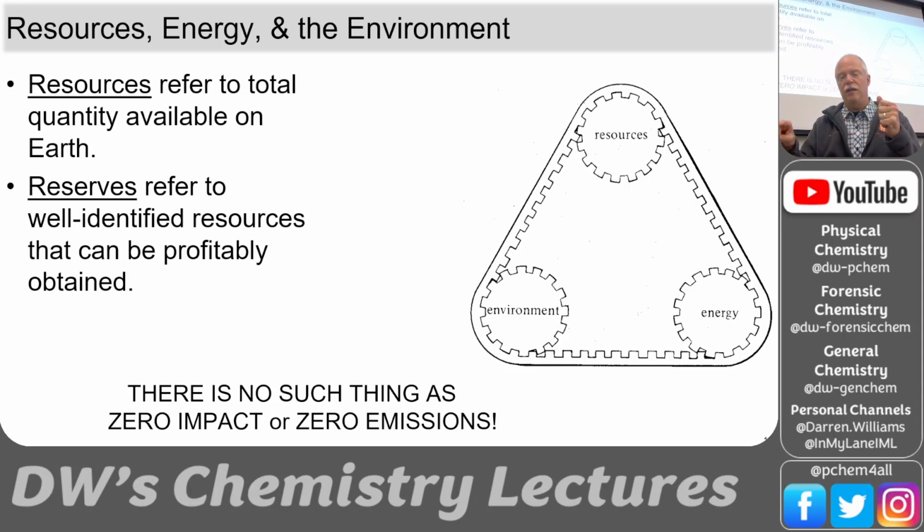So what they do is they get into that rock formation, then they plug the pipe on the top end. It's a horizontal well, but they plug the exit, and then they pump fluid in there at extremely high pressures, and it'll crack that rock formation and create a huge amount of surface area in the shale rock area. And so now, because of the new surface area, the natural gas molecules that are trapped in that shale deposit have a shorter distance to migrate through the rock. And so they'll migrate through the rock into the fractures, and then they'll make it out at a profitable rate. So that turned shale natural gas from a resource into a reserve.